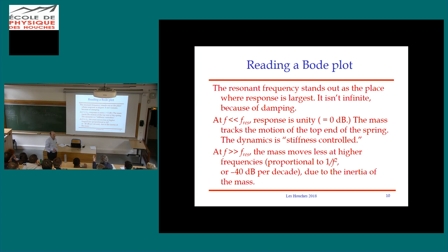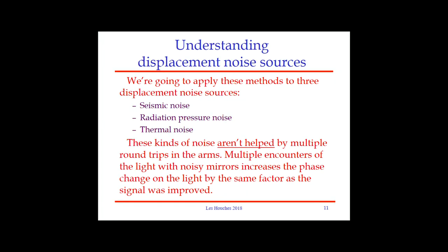To just make a comment, those of us who've driven oscillators know you don't want to drive an oscillator doing something for you on resonance. You want to be on one side or the other, right, for phase stability. Conceptually, though, thinking about the on-resonance case will prove to be really important. But generally, especially because we often are using very high Q oscillators, the last thing you want to do is drive a high Q oscillator on or anywhere near resonance.